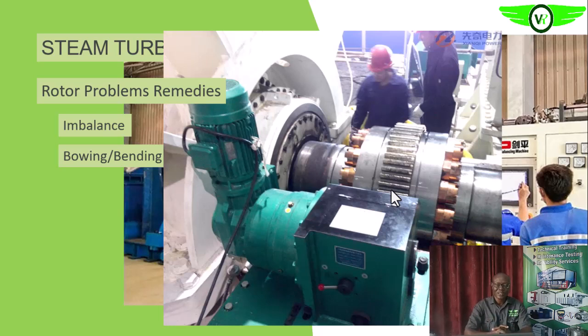Are we getting it? So that we do not have that temperature gradient along the rotor, so as to avoid bending. So proper use of our turning gear will help us to avoid bending.